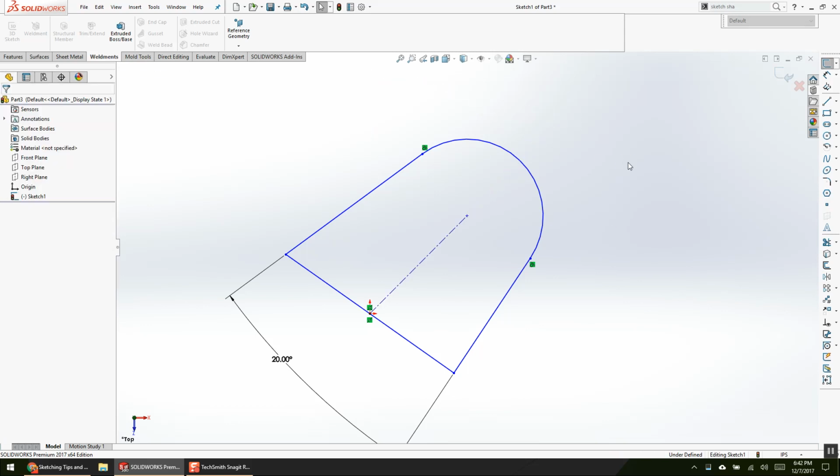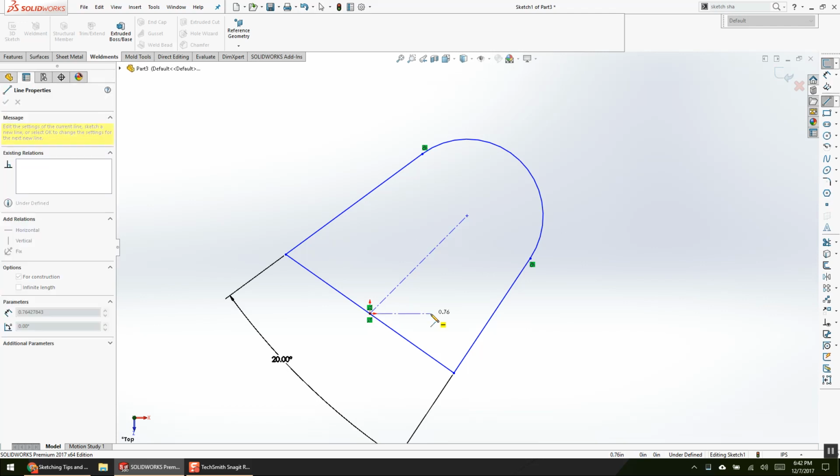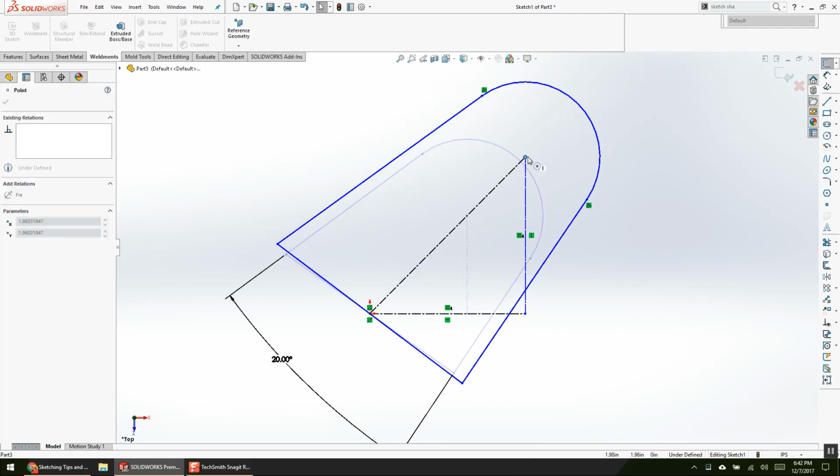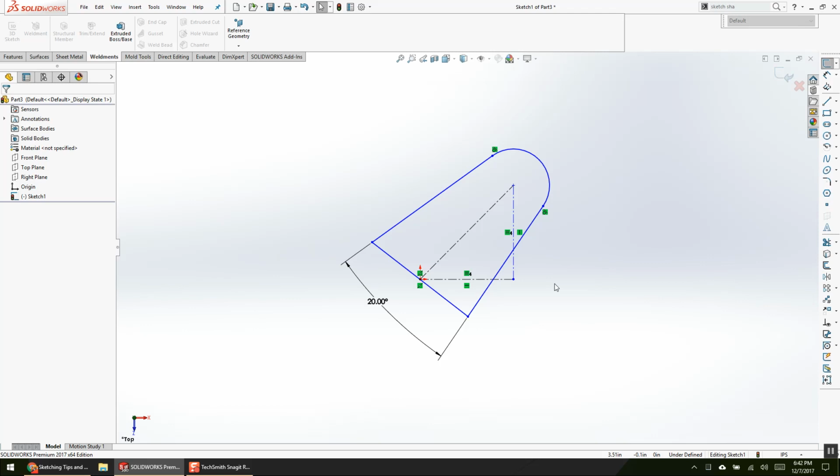Because every dimension I add is an implied liability. If I add a dimension, it can be changed. If it can be changed, it can get messed up, or it can get edited, or it doesn't communicate design intent as well. It's just an arbitrary value, arbitrary in the pure abstracted sense. If, however, I draw this and make those equal, what have I guaranteed myself? Because if you have a triangle with a vertical and a horizontal line that are equal, what angle is guaranteed mathematically? All of the time, every time, no contest, no question.